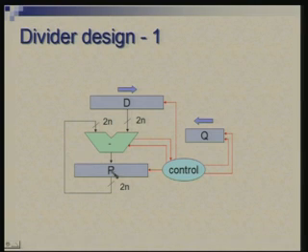We may not store it actually if the result is negative. Okay. So, basically we are assuming that there is an indication that the result is positive or negative, and this control acts accordingly. It will modify the value of R or not accordingly, and it will set a 0 or 1 in q as q shifts to the left. So, this circuit captures the straightforward algorithm which we had just worked out.